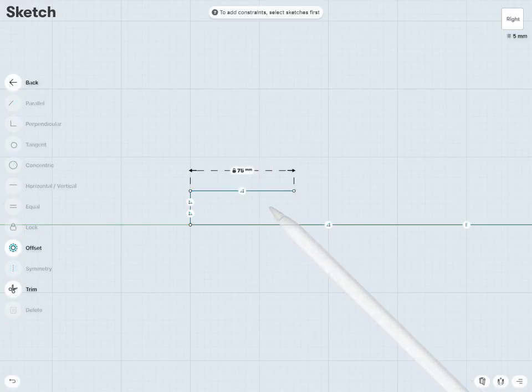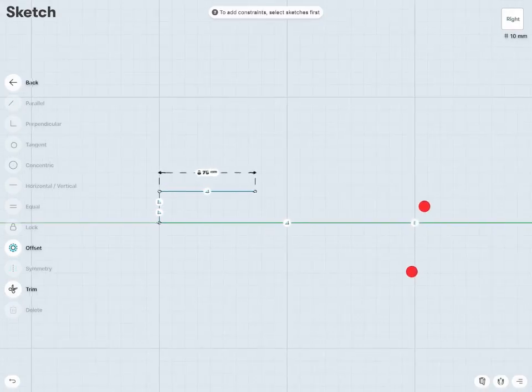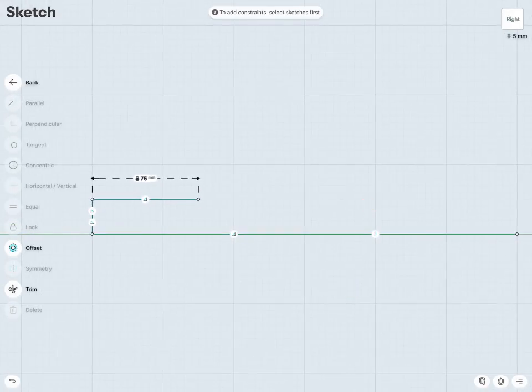And so I can say 75 millimeters there. Then let's say I have another portion of my main shaft where I have a larger diameter. So I'm just going to increase our radius here by, let's say again, another 25 millimeters, such that the larger diameter portion will be of a radius of 50.